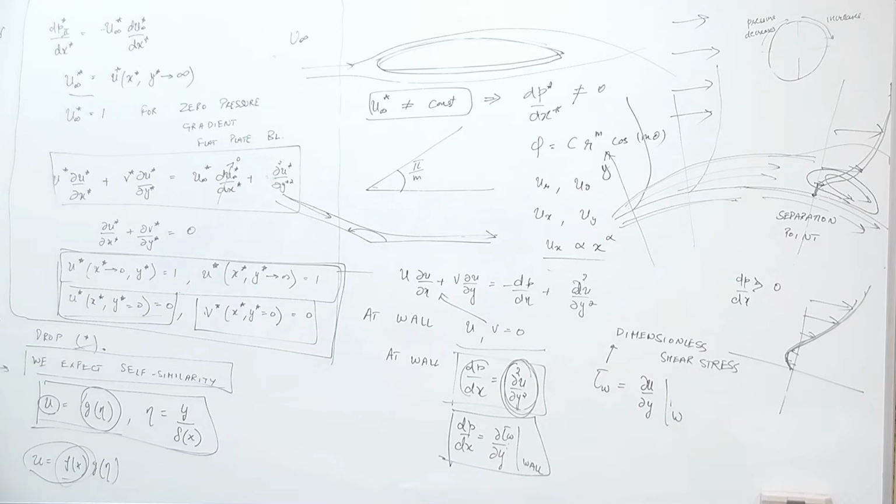And this boundary layer separation is the cause of major problems in all of aerodynamics. You don't want your boundary layer to separate. If you want it to separate, you want it to separate very reliably. You don't want to bank on the unsteadiness of the flow that results from this boundary layer separation,